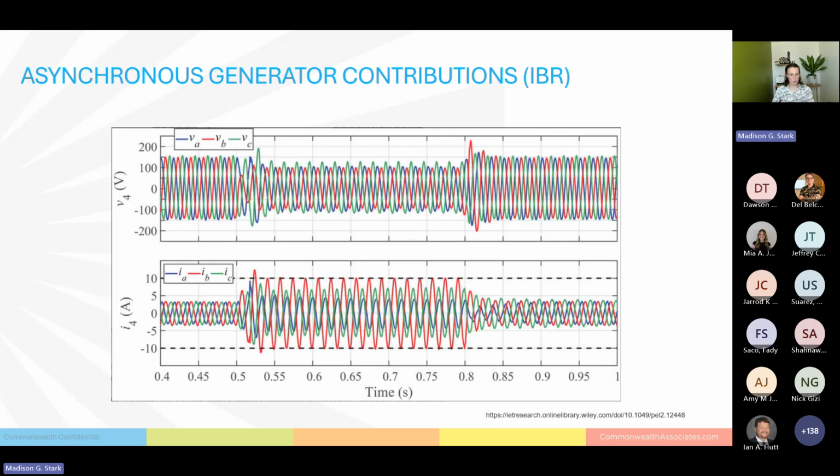And this is, again, what you might see. This is probably about that equipment rating, where you have that limited per unit value of the current output, and you see a slight voltage depression during that fault condition, but still within capabilities. And then again, this is the actual limit for about 0.3 seconds. So maybe the fault cleared right here, and that's why it shut off. But it can go up to about half a second from 30 cycles for that.